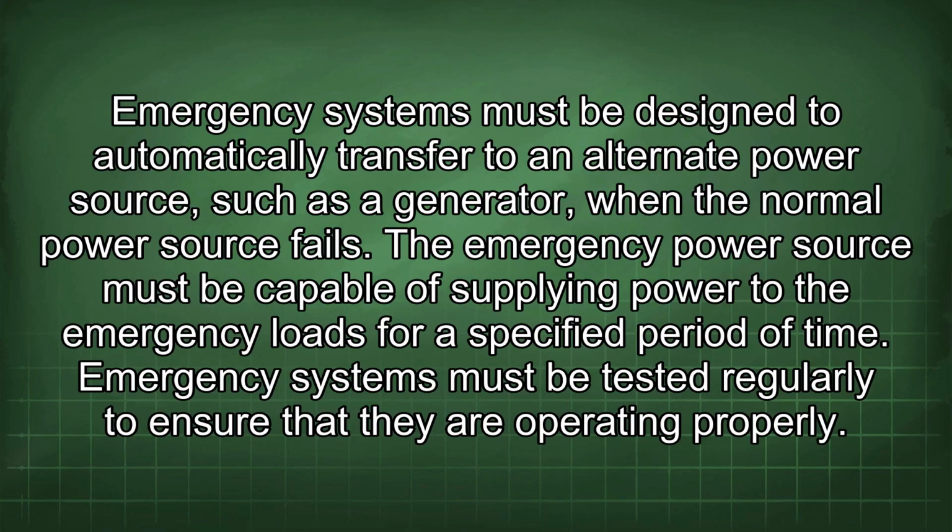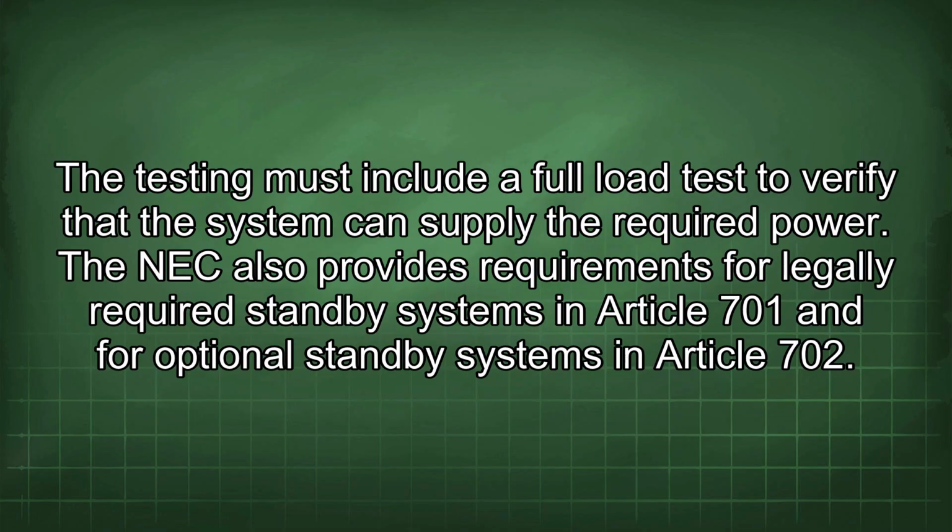The emergency power source must be capable of supplying power to the emergency loads for a specified period of time. Emergency systems must be tested regularly to ensure that they are operating properly. The testing must include a full load test to verify that the system can supply the required power.